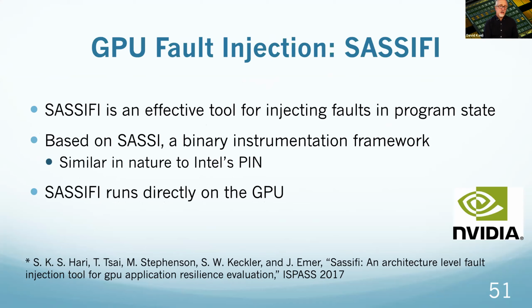So for a GPU, for fault injection, we have a tool named SASSIFI, which is built off of SASSI. SASSI is a binary instrumentation system, very similar in nature to what PIN is. And I recognize that there's even a more current version of SASSI that NVIDIA has now. But the SASSIFI tool was designed for Kepler GPUs, and basically allows you to run directly on real GPUs and inject bit faults in the actual state.